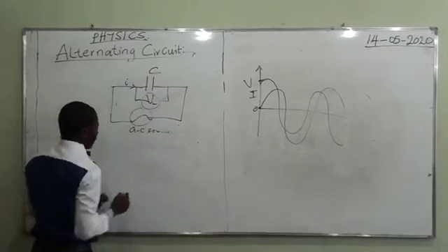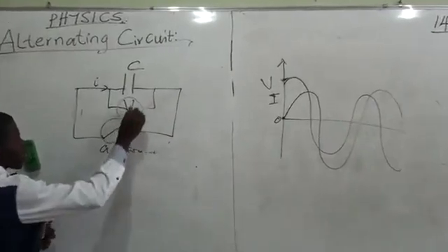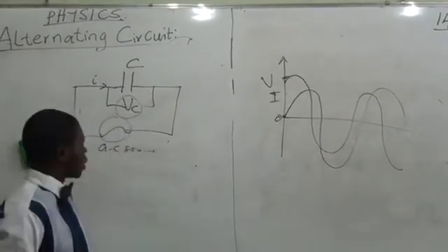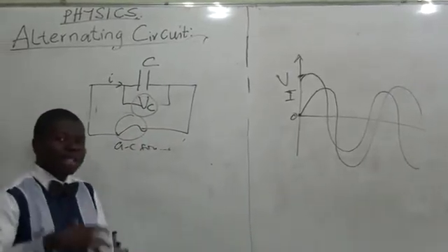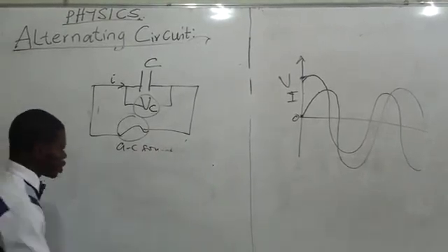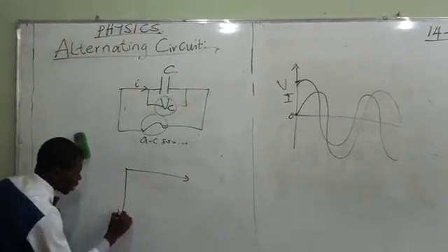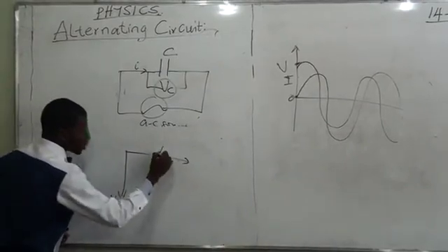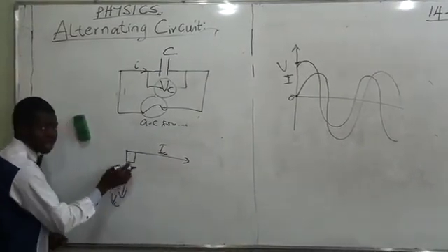You put C there. By the way, what is a capacitor? A capacitor is a device that stores electric charge, so it has electrical energy embedded. In this case, since a capacitor stores charges, there is more current accumulated in it. So this time around, current will be leading the voltage by 90 degrees. The representation for the vector diagram goes like this. You have the voltage for the capacitor going downwards. This is I subscript C, that's the current through the capacitor, and then the angle established is 90 degrees.